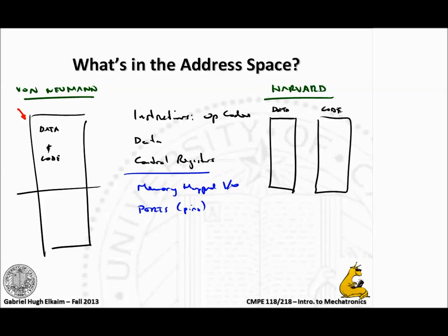So a number of years ago, there was a satellite called the Clementine that was sent out to map the moon, and they got a single bit upset event, which means they got hit by a gamma ray, which caused the program counter to shift. A one in a billion shot, but lots of cosmic rays bombarding it, and it caused the program counter to jump through data, and the thing basically started executing data as code. It managed to dump all of its fuel, firing the rockets randomly before the watchdog timer had time to kick in and reset it. So they lost the satellite. It's still spinning somewhere near an asteroid off between the moon and the L4 point. But anyway,